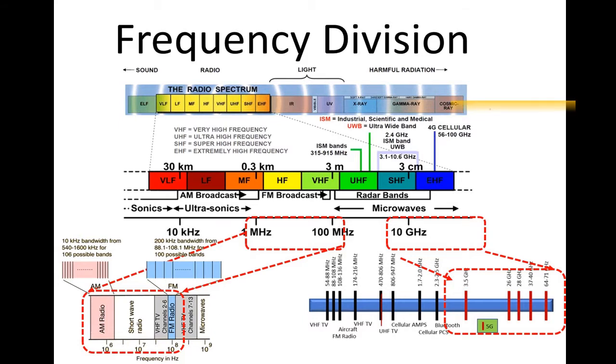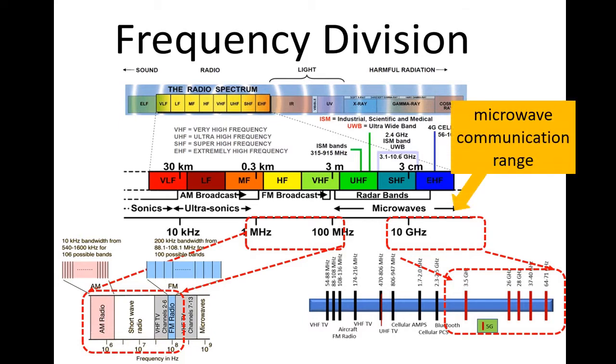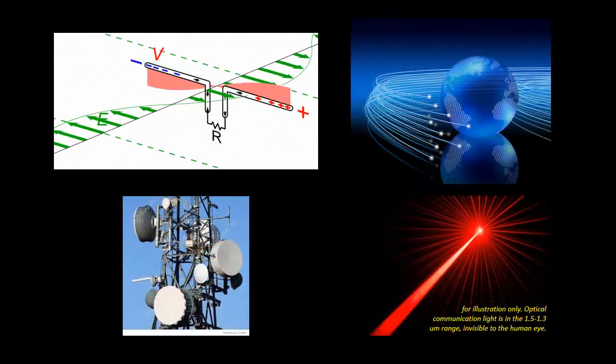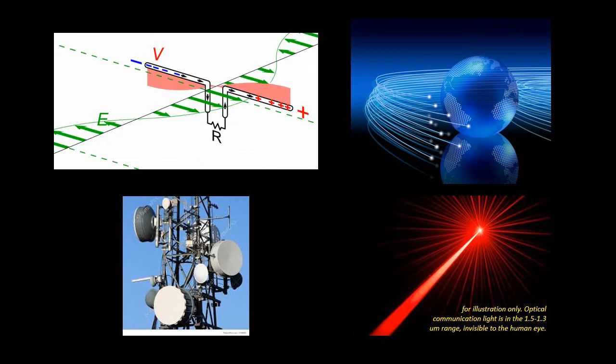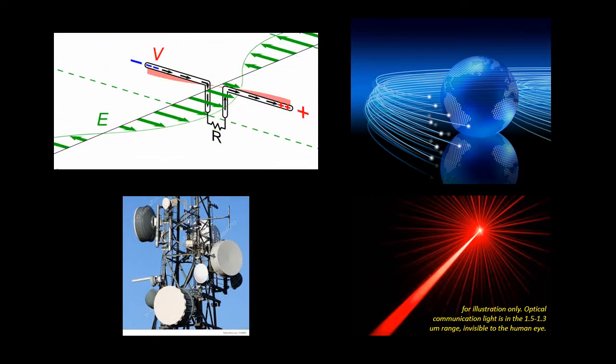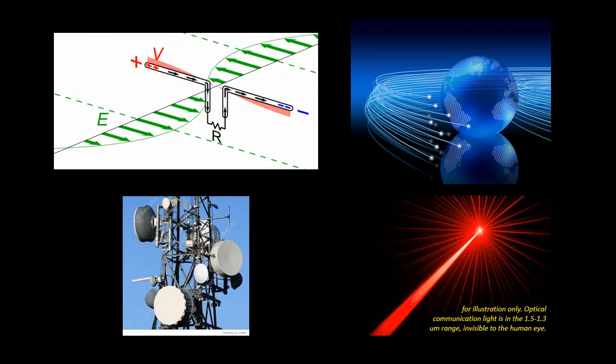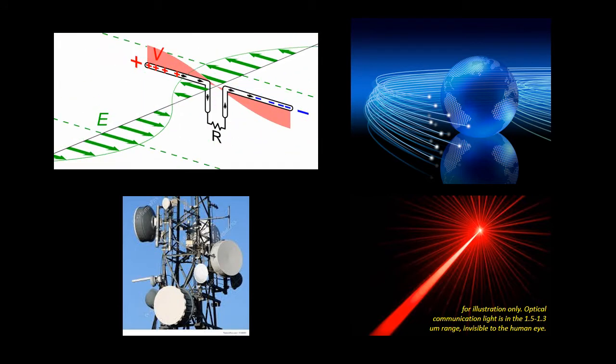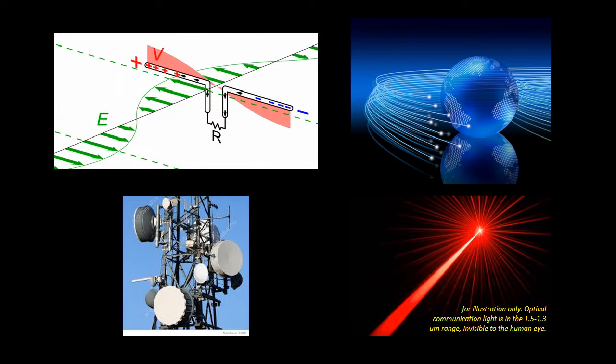More important for data communications are microwaves, from 2.4 or 5 GHz for the ubiquitous Wi-Fi, up to tens of gigahertz for advanced mobile communications network. Ultimately, all aggregated data from local area networks are carried by 200 terahertz light waves in millions of miles of optical fibers spanning around the globe, which is truly the engine of the Internet.